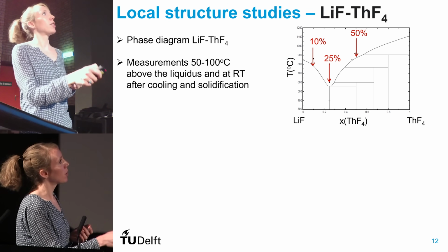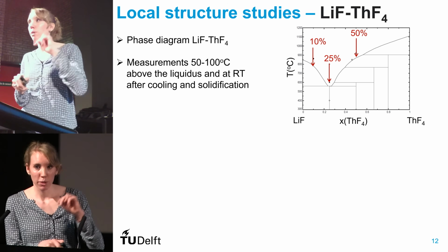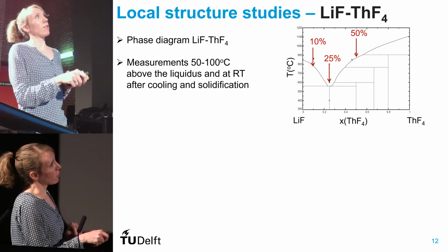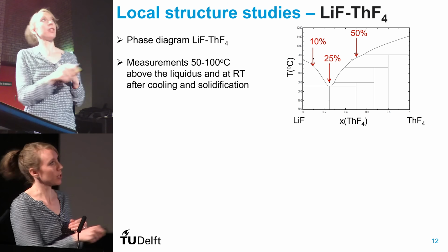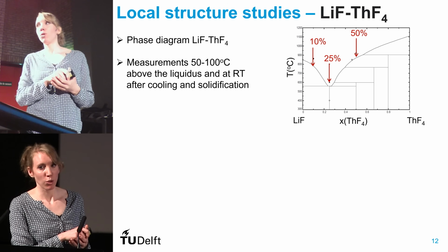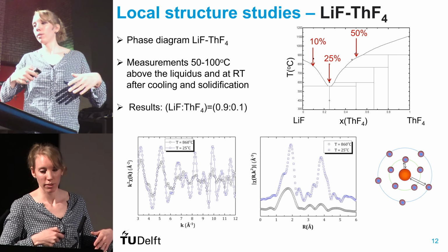So then we moved to measurements at high temperature. So we measured these compositions in the lithium-thorium system, and even 2 weeks ago we managed to measure pure ThF4. So what we do is we go 50 to 100 degrees above the liquidus temperature, so above this temperature, and we measure in the molten state and after cooling and solidification.